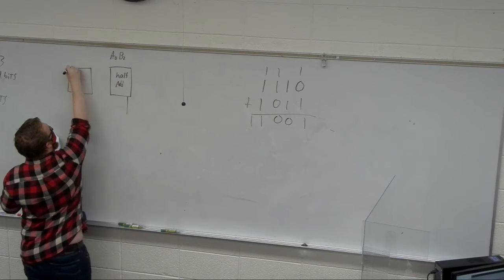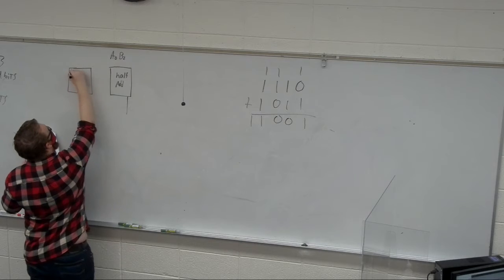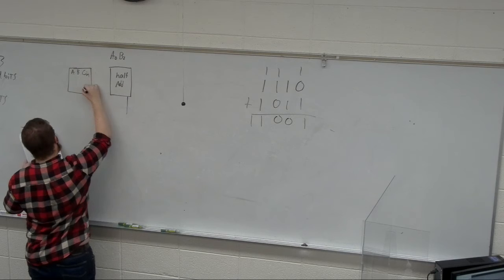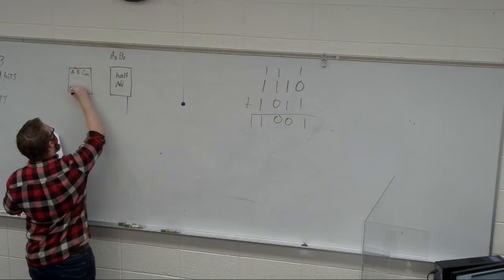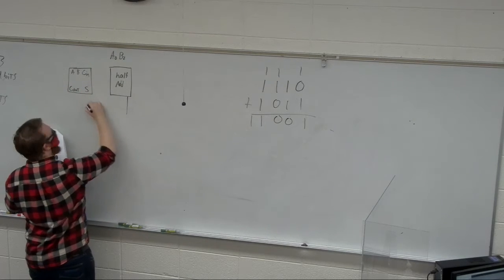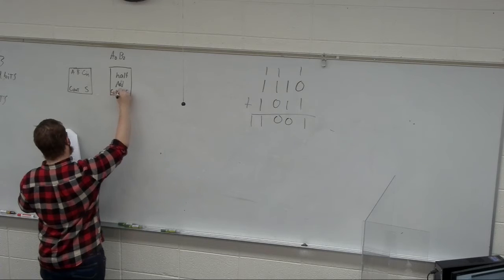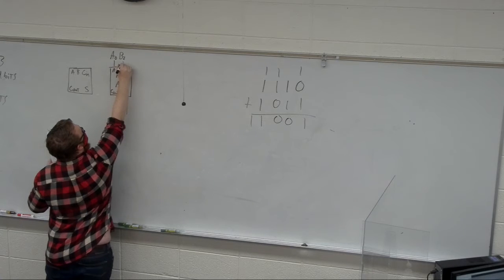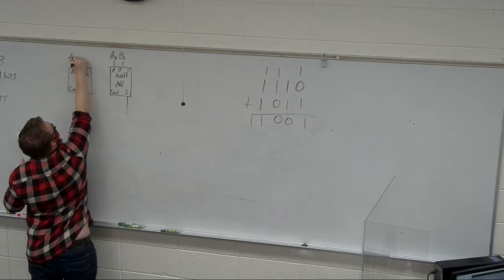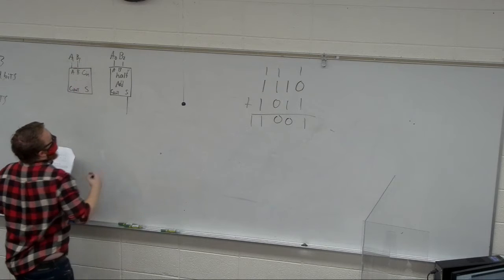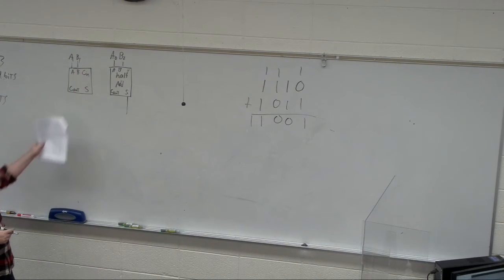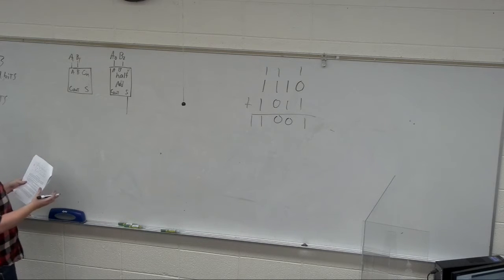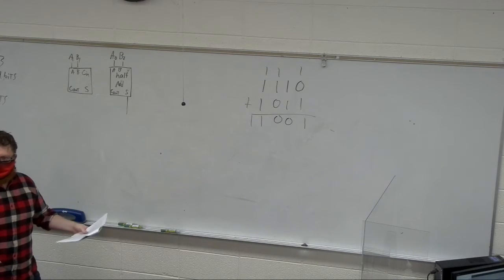And we're going to have a full adder over here. So each of these are going to have an A and a B input. They're going to have a carry in, a carry out, and a sum, right? So this is all the same, C out. This does not have a C in, it just has the A and B. So let's say I design each of these, which we will get to. They're not that hard, but I want to hook them up in such a way that they are now 2 bits.